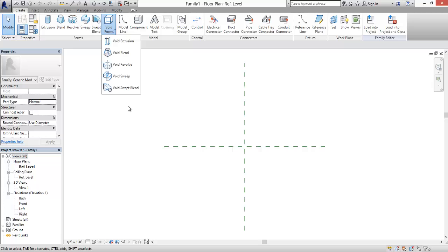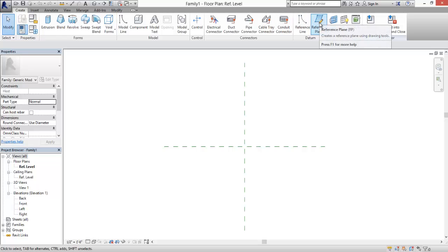You will find that you will have to be creative about how you develop some of those things and how you constrain some of those when you do some more advanced content. Okay. Over here, another key thing we'll be using is reference lines and reference planes. I prefer to use reference planes since they show up and you can constrain to other things and you understand how things work more intelligently.